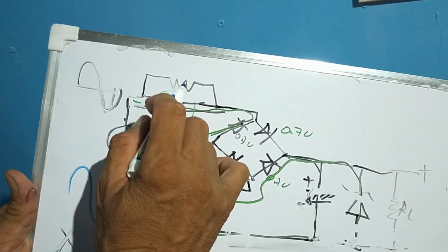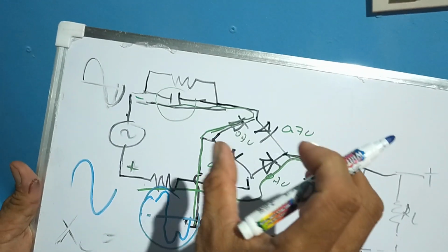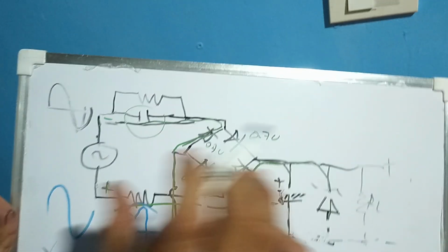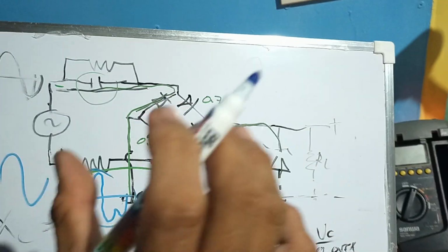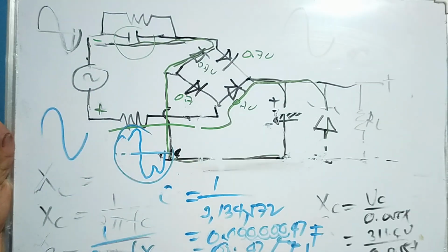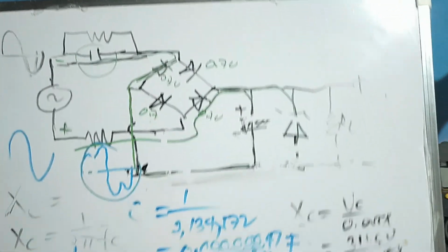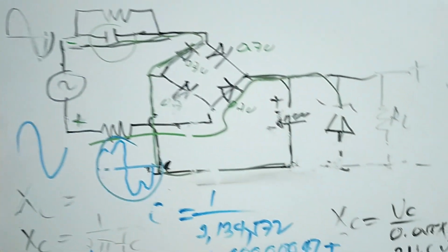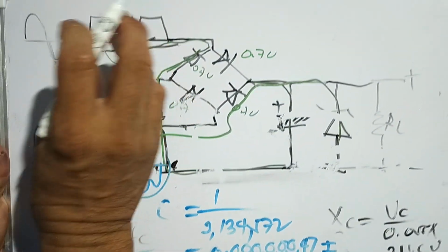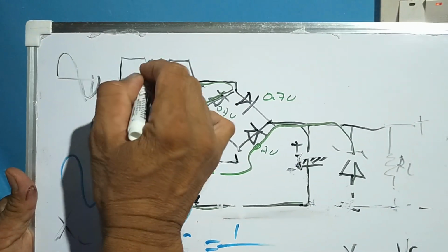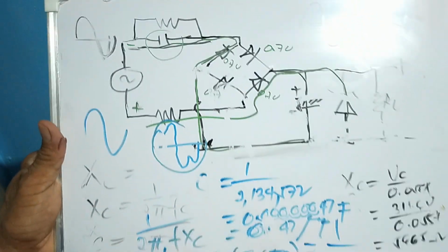This 1 megaohm resistor is just the discharger of the stored voltage of this capacitor, to prevent us from electric shock once you happen to touch any of the terminals here. Although the AC cord is already disconnected from the outlet, there is a remaining voltage across this capacitor. So, to remove that stored voltage, there should be a permanent resistor connected across it.